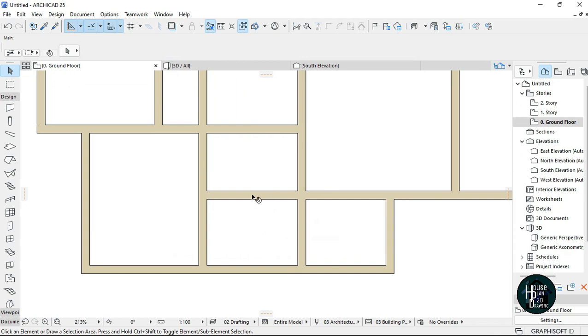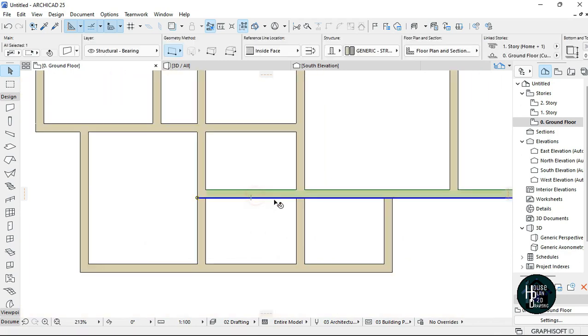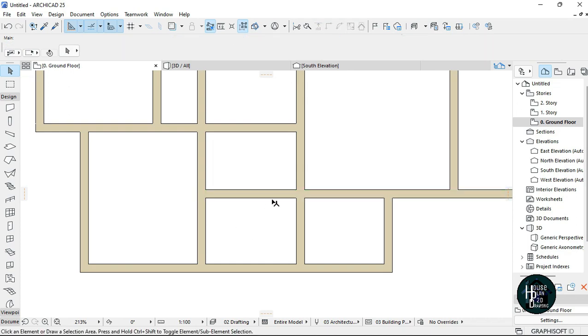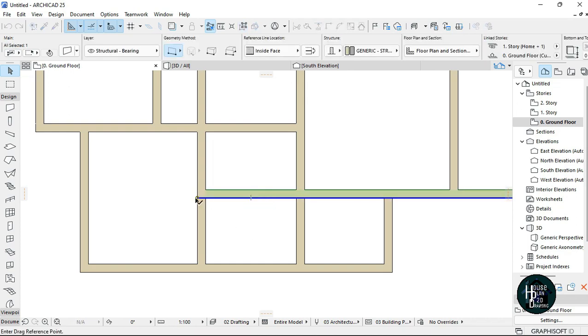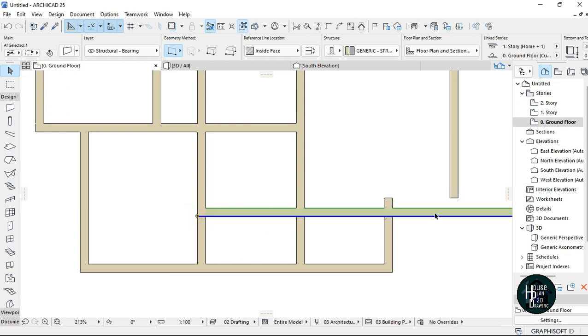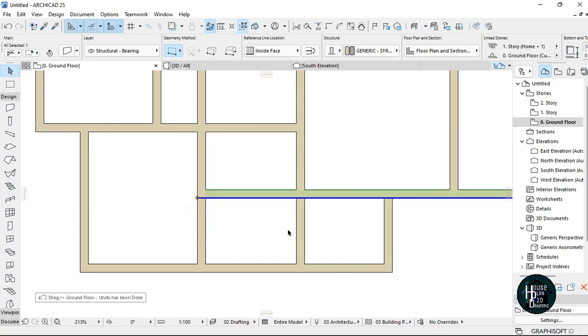At times when you want to cut this wall, okay, let me say you want to actually move this wall to this particular place, because if you actually move the wall, Ctrl D and move the wall here, it's actually going to select everything. So Ctrl Z to take it back.